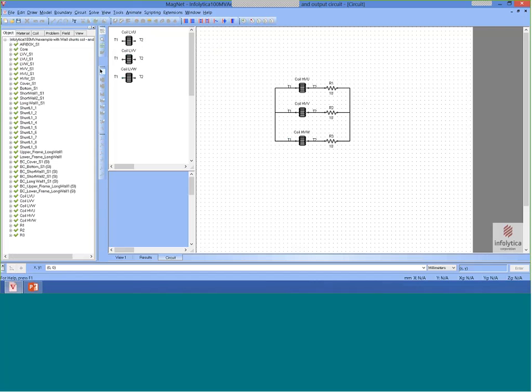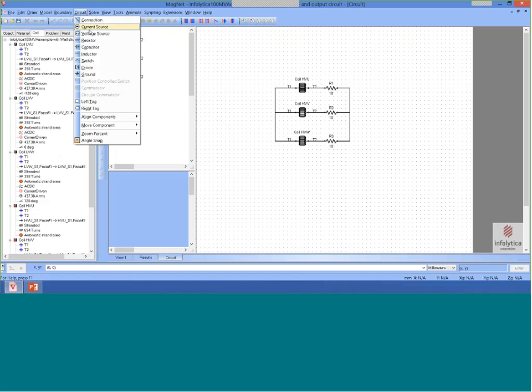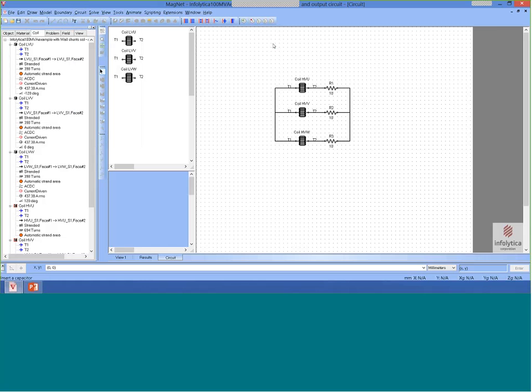And as you can see, we can create a circuit and leave other parts out of the circuit. If you look at the coils here, they already are current-driven coils. We have the number of turns. We have the current in each of the coils in its phase. But for the output side, we've just connected it up to a series of resistors. This doesn't have to be resistors. It could be capacitors and inductors as well, and so on.